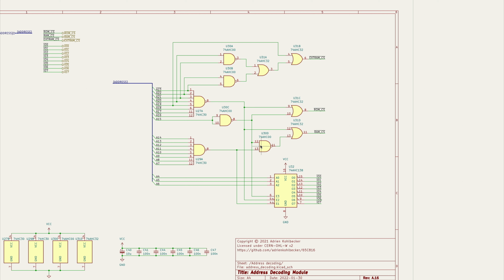And when we add the external RAM, we'll discuss what we're going to do with those pins. But most likely we're just going to leave them as is, because the RAM doesn't care if one of its address pins is inverted. It's just going to throw it at the inverted address, and we're going to be able to read and write this location transparently without needing to re-invert those pins.